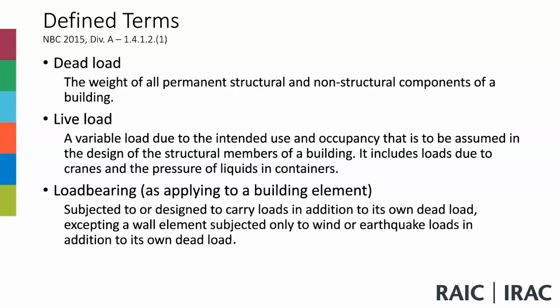Live load is a variable load that, due to the intended use and occupancy, is assumed in the design of the structural members of a building. It includes loads due to cranes and the pressure of liquids in containers. So this is where we're looking at the use of the building. In industrial buildings, we also look at the additional loads of cranes and liquids in containers.